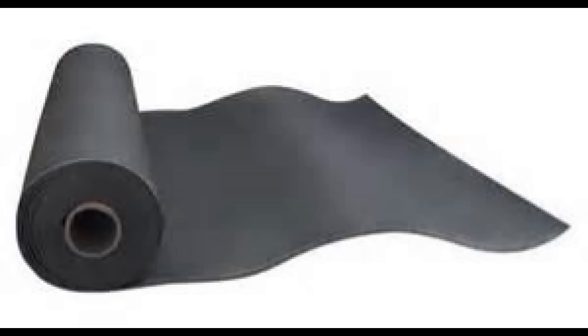Here's an example of mass-loaded vinyl. It usually comes in a roll, or you can get it in sheet form. It's usually 1 pound per square foot is how it's usually designated. You can get half pound, I would not recommend it. You can get 2 pound per square foot mass-loaded vinyl, which, especially if you're dealing with lower frequencies, would be highly recommended.